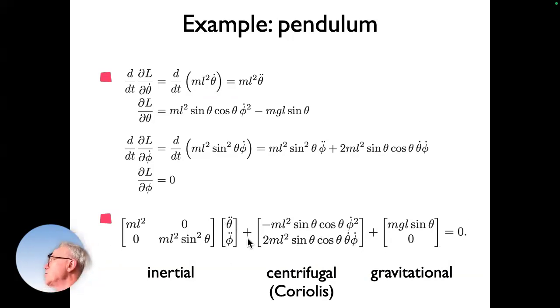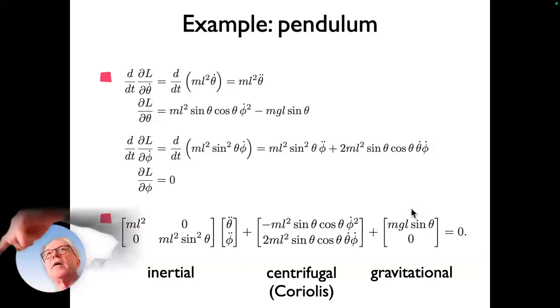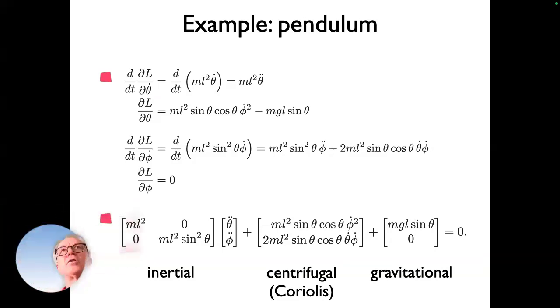They have the acceleration terms here. In front of them is a matrix. We call that the inertial matrix. And then there is a term that contains joint angles and their derivatives in some complicated form. That's actually just centrifugal terms. And then there is a vector that only depends on the joint angle. That's the gravitational term. For the theta phi variable, there is no gravitational term because that is a variable that keeps the elevation of the ball in a plane, and only for the other one is there a gravitational term, and that is zero if there's no actuation in that.